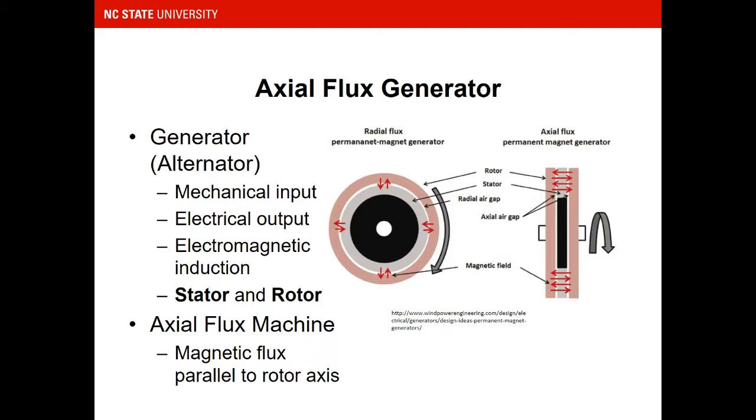For this demonstration, I've built an axial flux machine in which the magnetic flux acts in the direction parallel to the rotor's axis. It's typical to have a second rotor positioned on the opposite side of the stator. However, for simplicity, I chose to include only one.